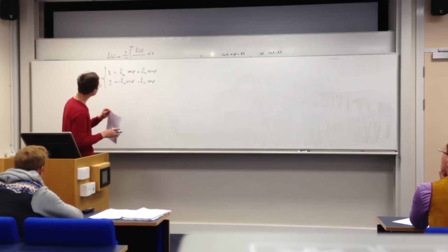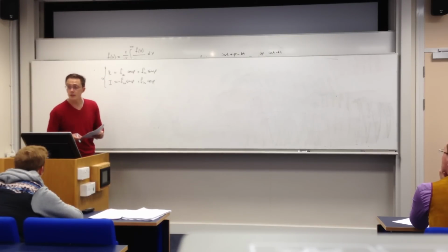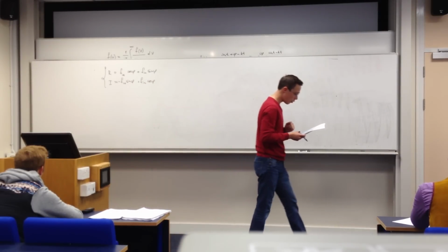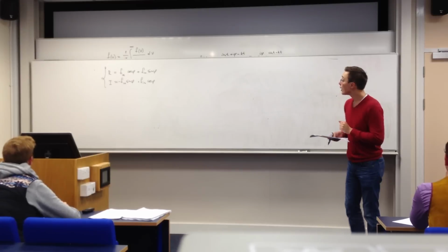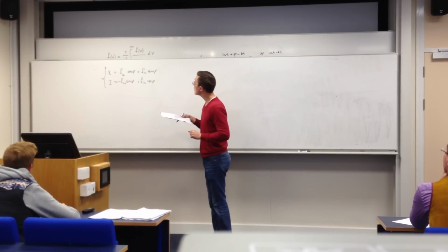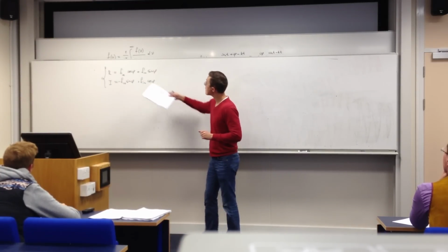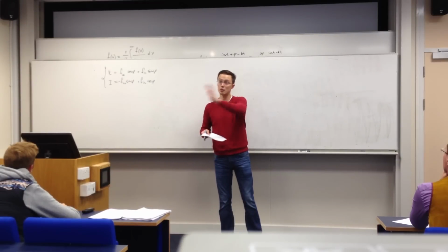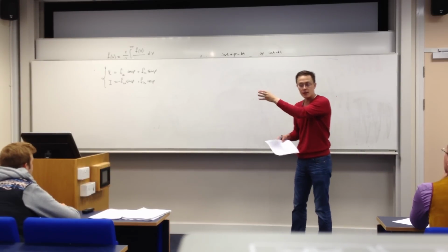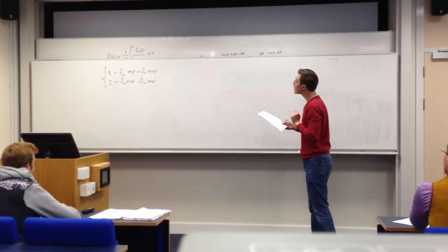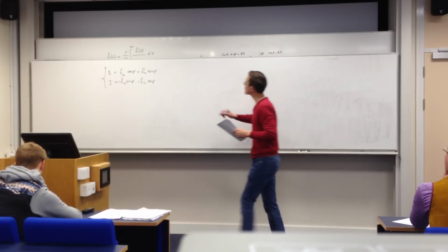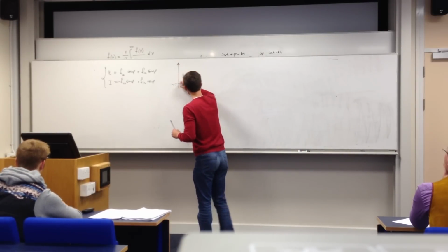Now, it all would have been easy if it was just a single phase. This simply is a transformation which would be the same for every frequency. But it so happens that phase distortions in the spectrometer are almost always frequency-dependent. Oftentimes what happens is this phase depends on where the signal is. If it's on the extreme right, the phase distortion has one phase, and if it's on the left, the phase distortion will have a different phase. And the reason for that is usually rooted in the modulation theorem for Fourier transform, I will remind you what that is.